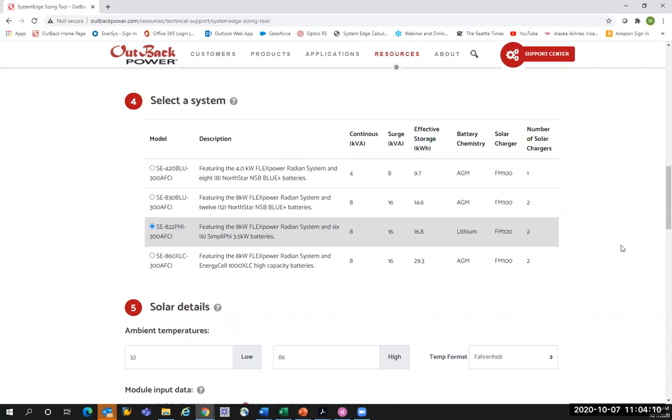That there's just going to be surge with a microwave. I don't know how you're going to... I don't think a soft start is going to work with a microwave. At least I've never heard of it, and I don't see manufacturers that spec it. But with motors, for sure, and a lot of people get locked rotor confused with inrush current.